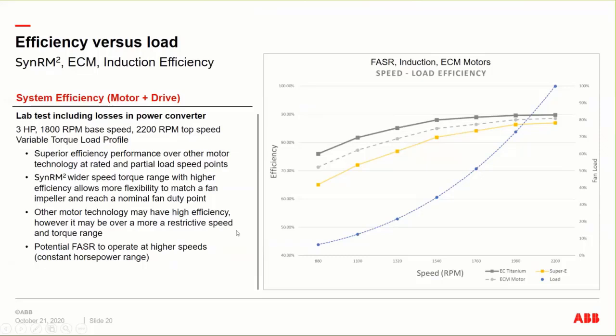And there can be a wide efficiency difference because there's just a lot of variables. So if you look at a fan design, there's a lot of variables associated with picking the right fan. You've got the speed of the fan, the diameter, the wheel width, number of blades. So when you get into the fan selection programs, there's a lot of variables there, and you can get really wide differences on these curves to the efficiency of the fan, and it's the primary contributor to efficiency losses at partial load and speed.